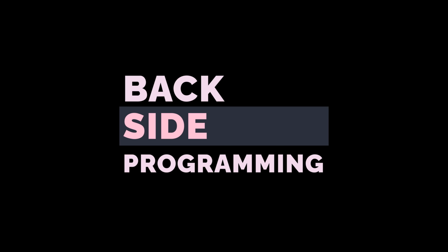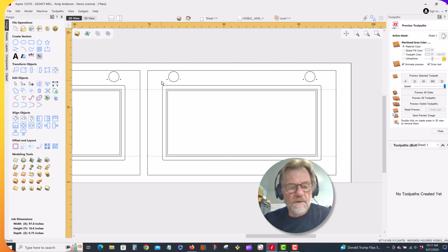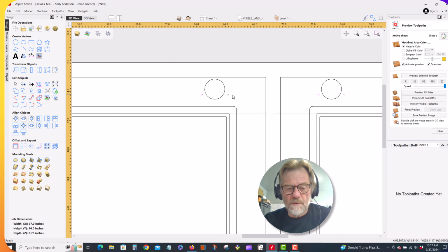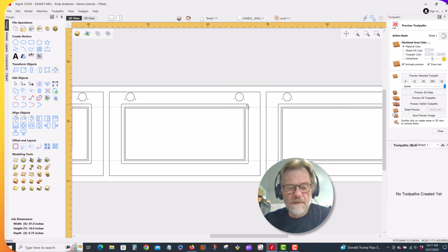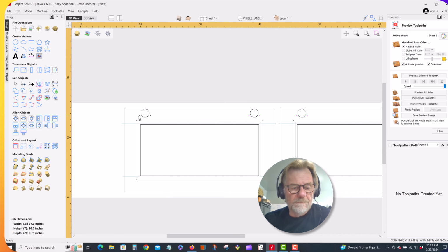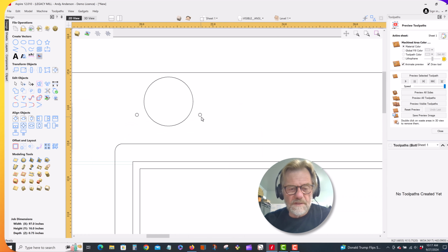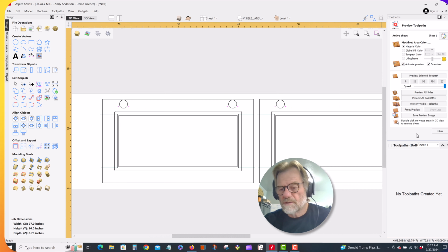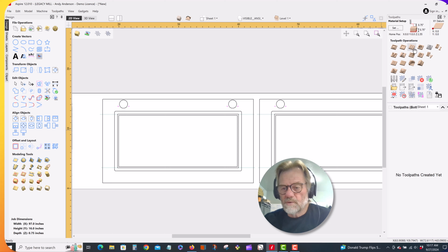First step, let's get the little details out of the way. So if we grab all these small holes, again, everybody's going to do this differently, but I pilot these with an 1/8 inch drill bit, 0.650 deep, and then I like to use stainless steel wood screws to hold my hinges in place. My hinge pockets are pretty tight, so most of the mechanical strength is actually relying on the tightness of the hinge.